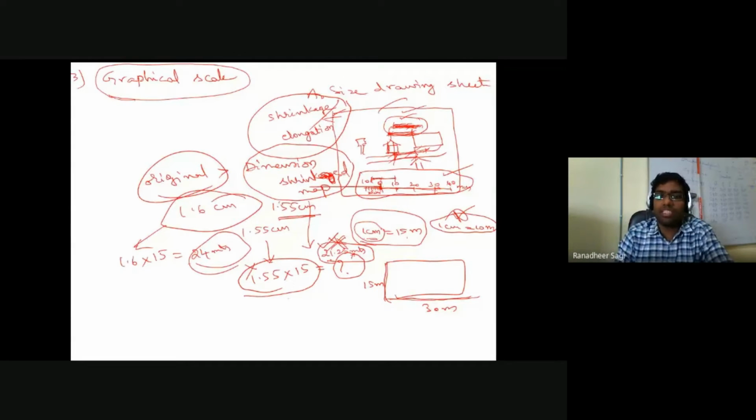are automatically taken from the graphical scale on your map. If I measure that dimension and get 1.6 meter, and it is converted with the help of your engineer scale, then automatically you are going to obtain the true measurements you had in the field. Without doing that, if you directly convert by measuring the original distances at which those two buildings are apart with your engineer scale, then the shrinkage that took place in the map, or maybe an elongation, is not going to be taken into consideration.